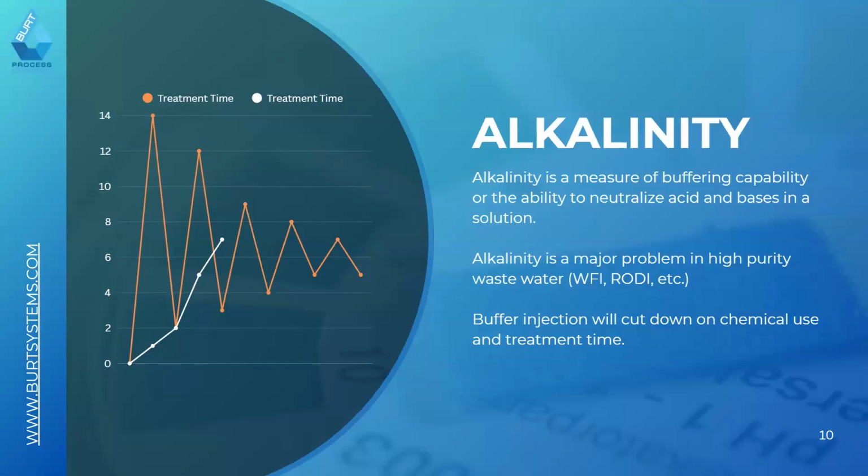When you're doing pH treatment, it's important that you have some level of buffering, so that you can see here on the right a smooth curve that comes with treatment. If you're down around pH 1, you want to be able to move almost in a linear fashion as you're looking to proportionally treat based on the pH curve.